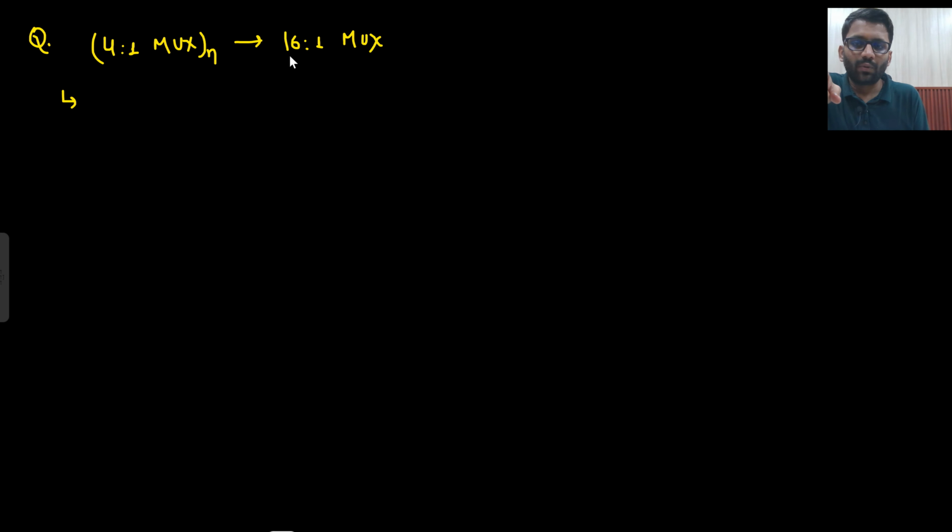Now you need to implement 16:1 from 4:1. So how many will be required? The same thing you can do. 16 divided by 4, what do you get? 4. 4 divided by 4 is 1. So next you are not going to do any more. So 16 divided by 4 is 4, plus 4 divided by 4 is 1. So the answer is 5.